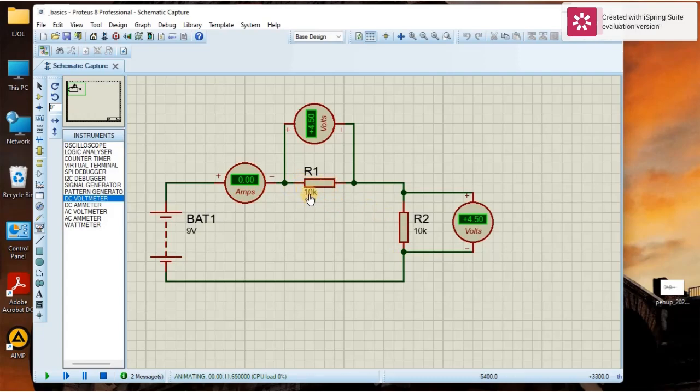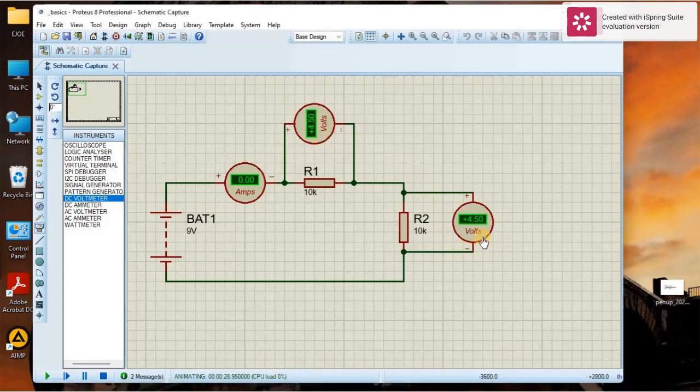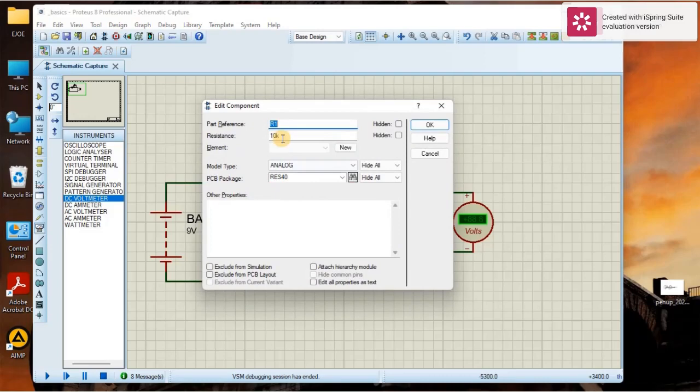It's too high compared to the voltage, so we basically don't have any current flowing through. Everything is blocked from flowing, so it would almost register 0 current, although there's a little bit of current, but due to the precision of this, we can't detect the current flowing, and the voltages are rounded off to 4.5, which adds up to 9. So meaning there's nothing flowing. If we lower the resistances a bit, we should be able to detect some current.